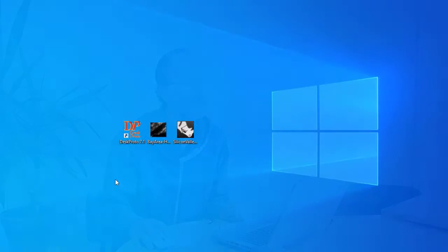Next step obviously is to start DeskProto, load that CAD data, that PNG file as bitmap file, and create the toolpath. I will show you how that can be done. As you can see, I prepared an almost empty desktop. Here's DeskProto. This is the relief file, the bitmap file, sorry, that I just downloaded. And here we have a DXF file with the text we engraved. I will come back to that later.